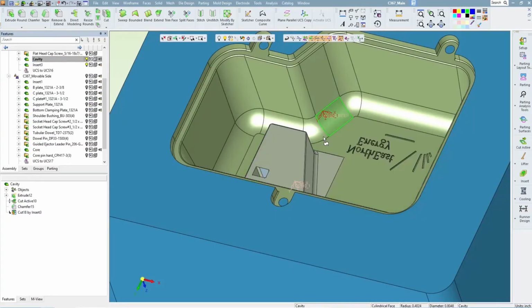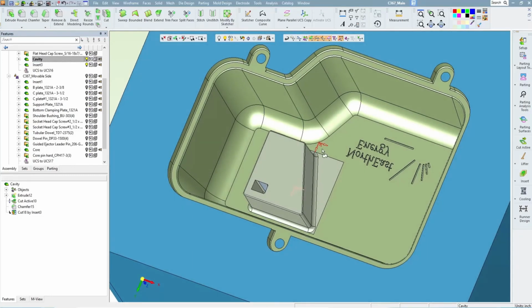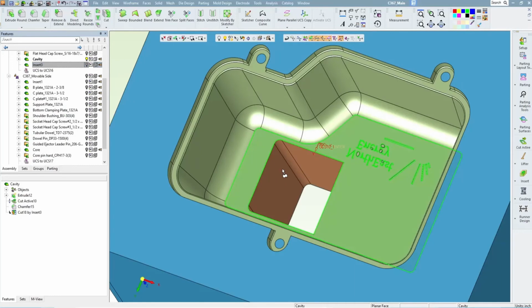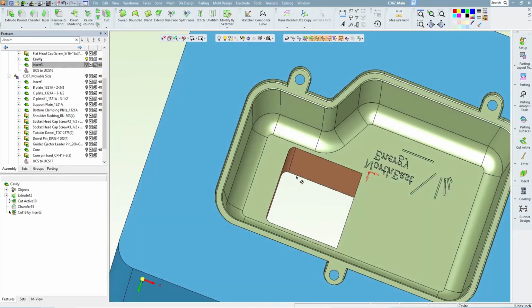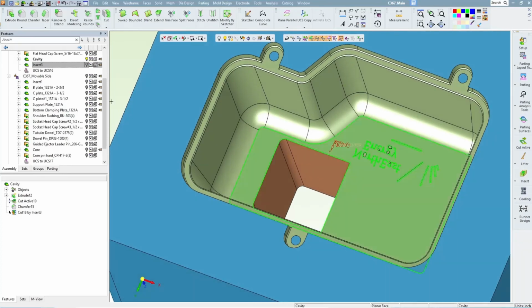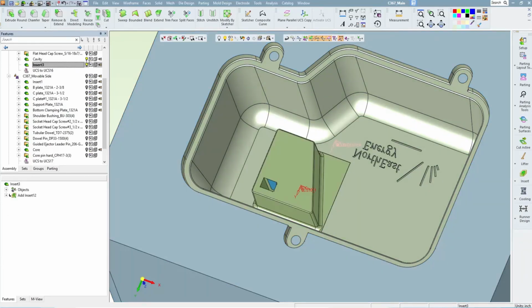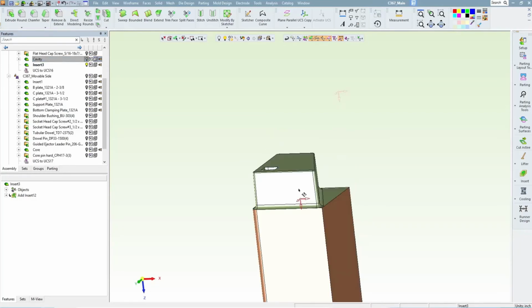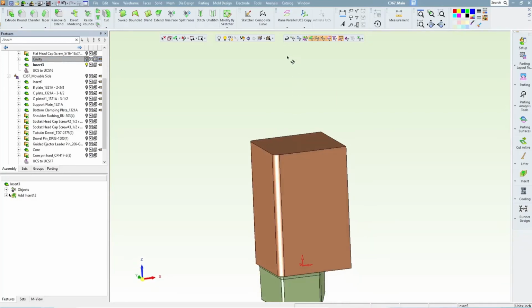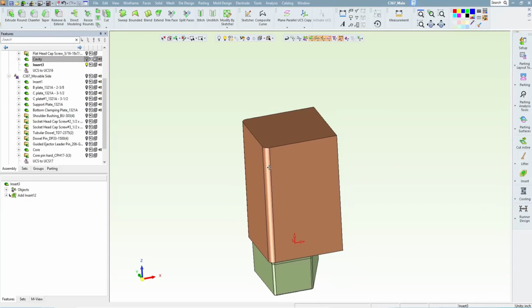So you can see that the new insert was created from all of the geometry that was found inside the 2D contour and within the depth setting numbers. In the cavity, a pocket is left behind. This insert gives me a chance to talk about the wedge function. Wedge is for automating different types of heels on inserts so that you don't have to add a screw to hold it in place.